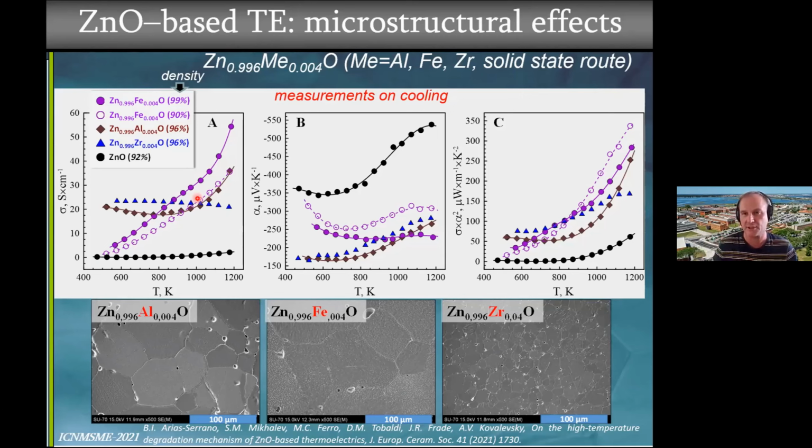When you sinter strontium titanate based ceramics at high temperature, then you cool down in reducing atmosphere, and if it is dense, everything is compact in the bulk and it is not exchanging. But when you have any open porosity, you can ask where is the oxygen in a reducing atmosphere? This is a good question. But you may still have some water, and water may act as an oxidizing agent. That's what I think.